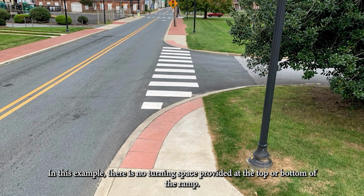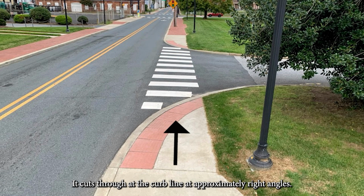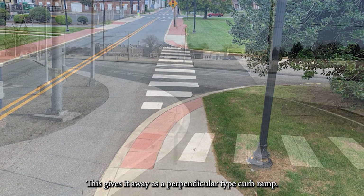In this example, there is no turning space provided at the top or bottom of the ramp. The key indicator of the type of ramp this is the orientation of the ramp segment. It cuts through the curb line at approximately right angles. This gives it away as a perpendicular type curb ramp.